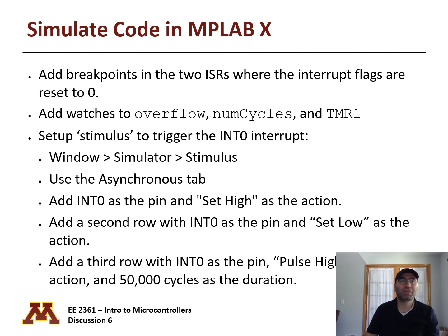Again, these are the steps. Just follow these steps. Add breakpoints in the 2 ISRs where the interrupt flags are reset to 0. So not the beginning of the interrupt, I mean just the line that resets the flag. Put the breakpoint there.